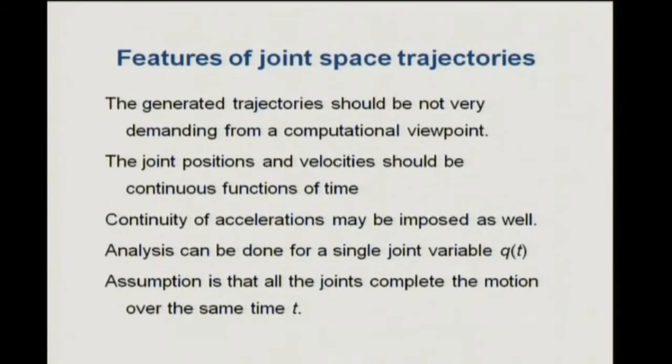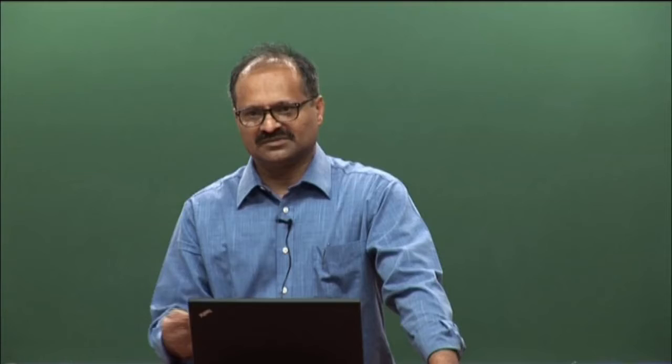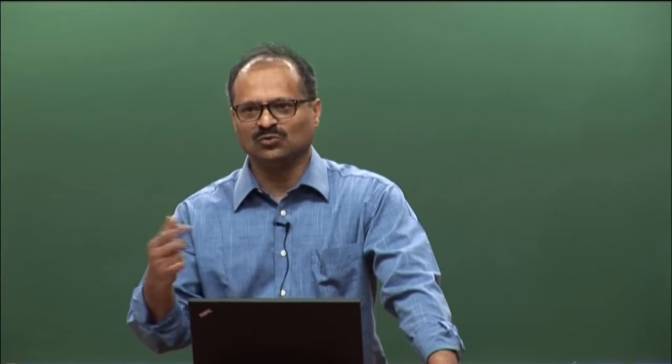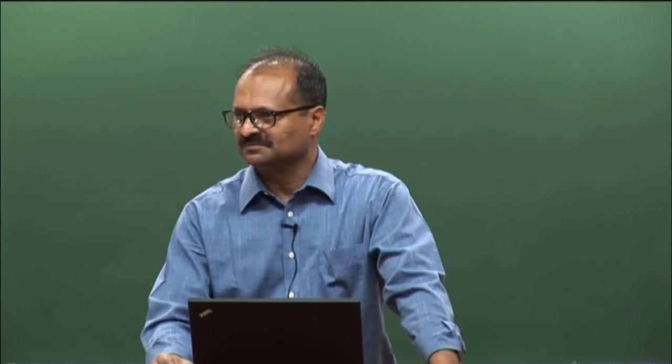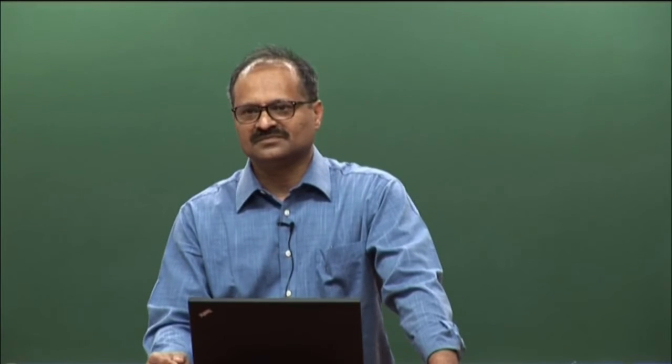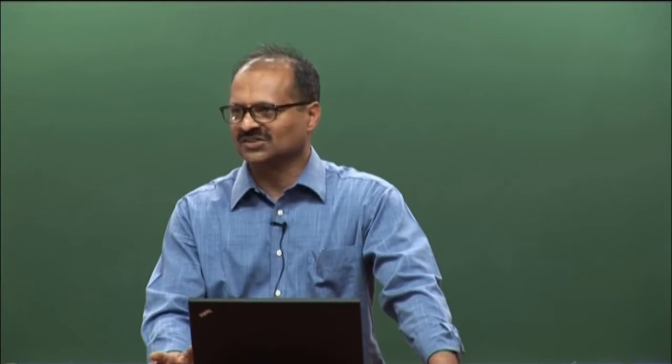Okay. So, what are a couple of features that we want in this? We do not want to do too much computation. Why? We want to write it into hardware, very simple. So, from the computer I might interface with the motor driver maybe at 60 hertz, 50 hertz, but the driver typically runs its loop in the megahertz range, closing the loop internally with the motor. So, most of these computations that I will discuss today are actually done on hardware. So, I do not want it to be very complicated, because then you have a problem.